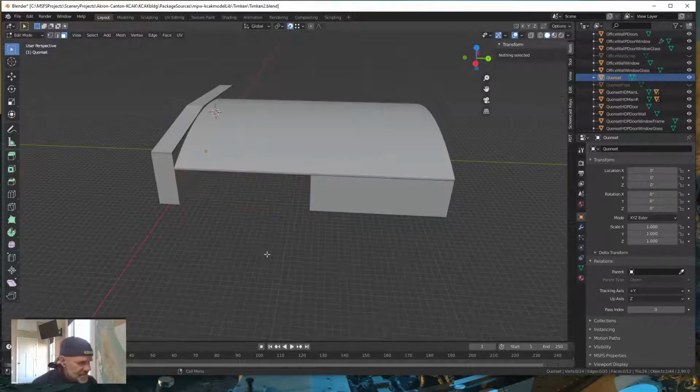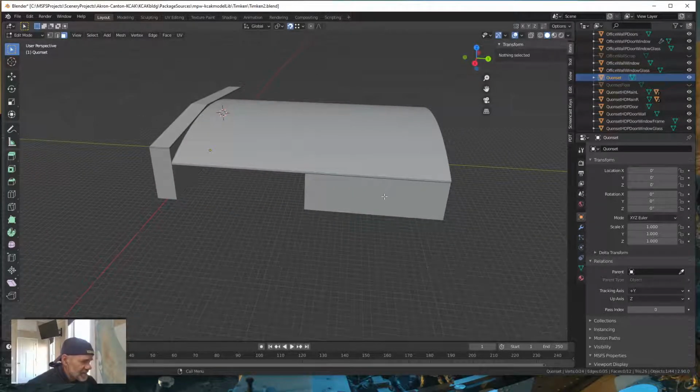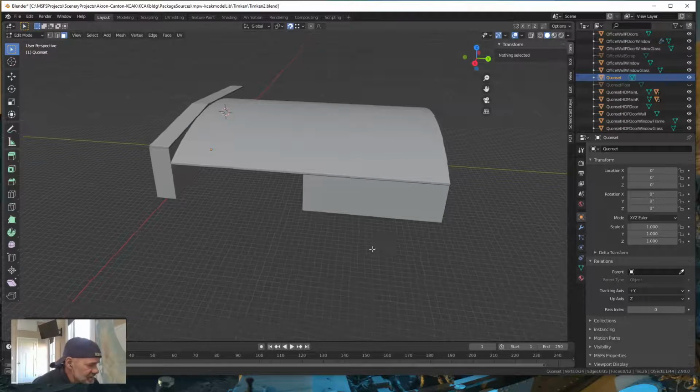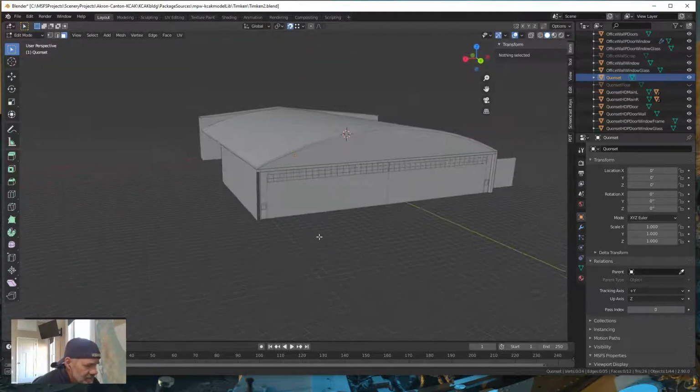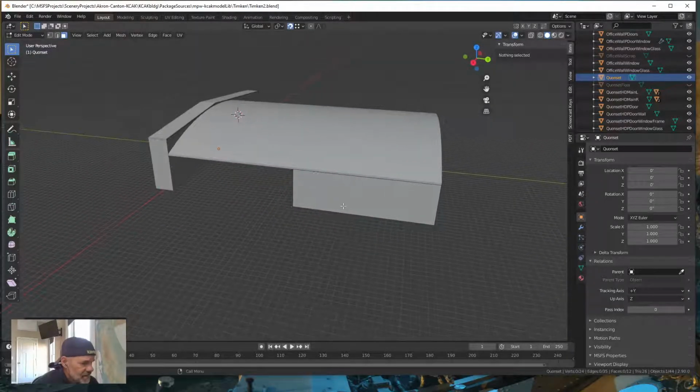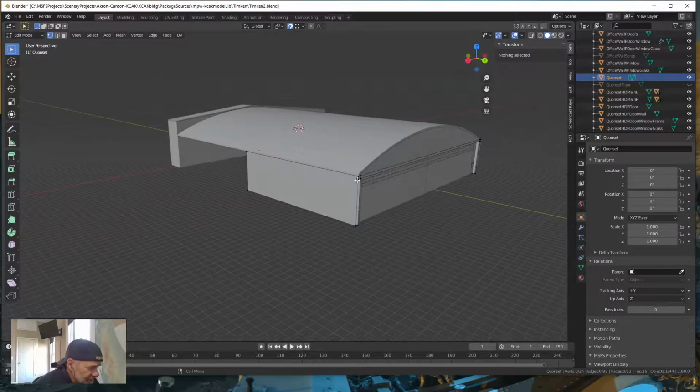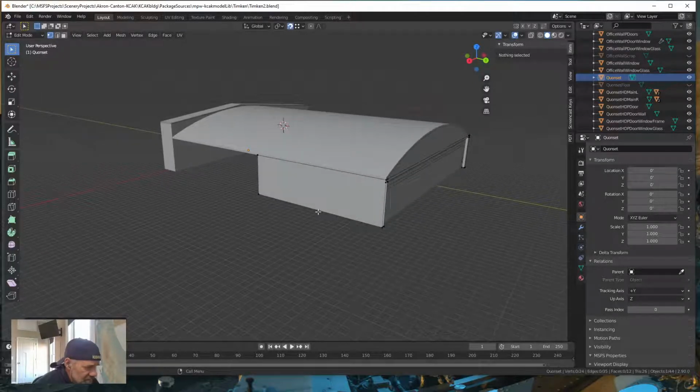Let's press H to hide those, and then come into this poly, press Control H, and I don't believe it's going to let me because I might have too many vertices to play with. Yeah, see, I've got this extra vertex up here that's causing our loop cut not to work, which is pretty typical for that kind of stuff to happen.